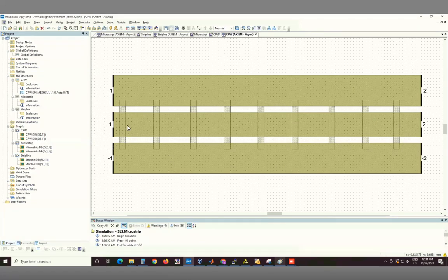Okay, this is slightly subtle. I'm going to move this here to make it very clear. There are three types of metals. There is the original ground plane. Then there is this square, which is a connection from the original ground plane up to this dummy layer. So that's a metal which goes up like this. Similarly on the other side, and then there is this extra metal layer which I have drawn, which is now on a different layer.